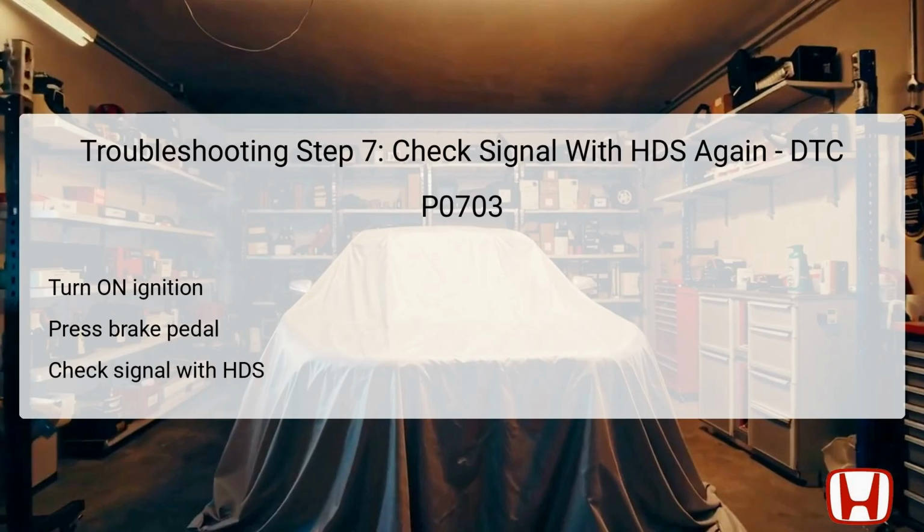If the current conditions match the threshold, it suggests that the systems are operating normally at this moment. However, if they do not match once again, you will need to proceed to the eighth and final step to thoroughly evaluate the brake pedal position switch itself for any functional failures.